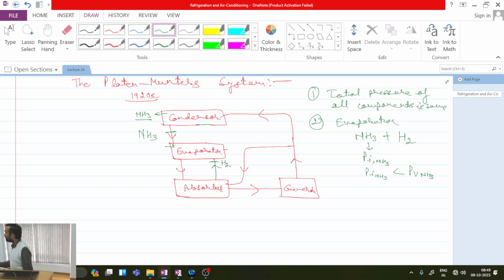Corresponding to that situation, the pressure of water vapor will be maximum in the mixture. Once air is saturated, in this room if I have saturated air and I have put the glass of water, even if I come after 10 days and in all the 10 days my air is saturated, will I have any level difference? There will not be any level difference.